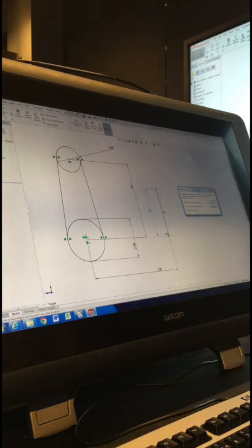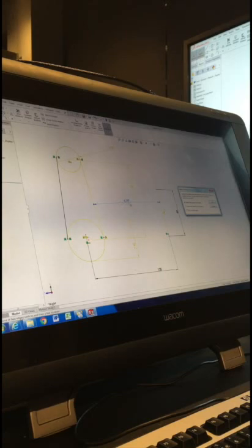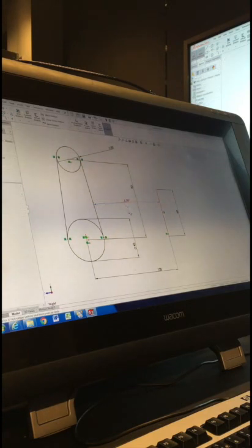All right, so driven would mean that, yes, I can have a dimension there, but it's not going to actually do anything. Another example of that is, let's say, between this line and this line here, which is on an angle, they're already fully defined. So that angle is not actually going to change anything, but I can leave it driven, which makes it grey, and it means it will tell me what that angle is.